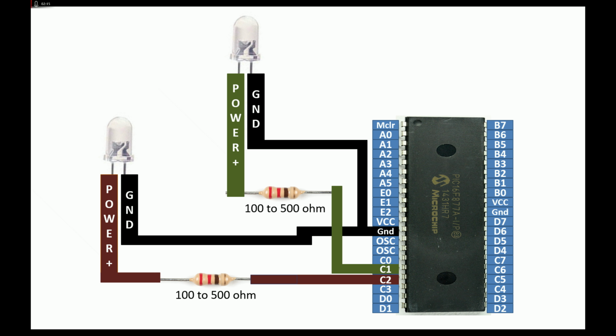Now of these 2 pins, pin number C1 is the CCP2 pin, and pin number C2 is the CCP1 pin. Pin number C2 is PWM1 and PWM2 is pin number C1. So in the datasheet, you may see CCP2 and CCP1. So this is PWM1 and this is PWM2. Only 2 pins in the PIC16F877A are dedicated for PWM generation using the MikroC libraries. If you use any other pin, then you have to go for another type of programming. You cannot use these libraries on other pins.